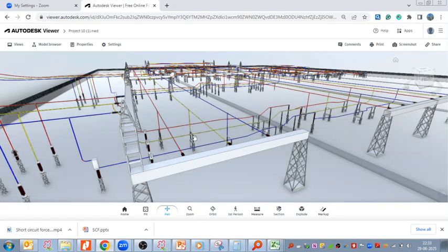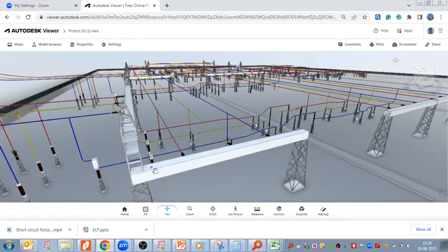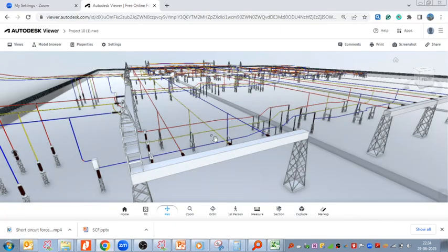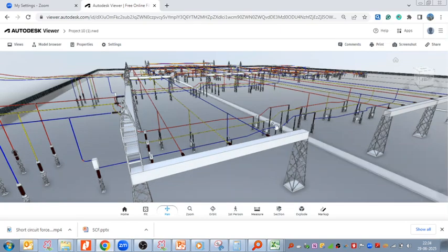So in that project, 27 meter was my base span. So 27 meter we have divided, from the center of this tower to first 6.5, then 7, then 7, then from here to the center of this 6.5, like that divided. So 7 meter between phases.